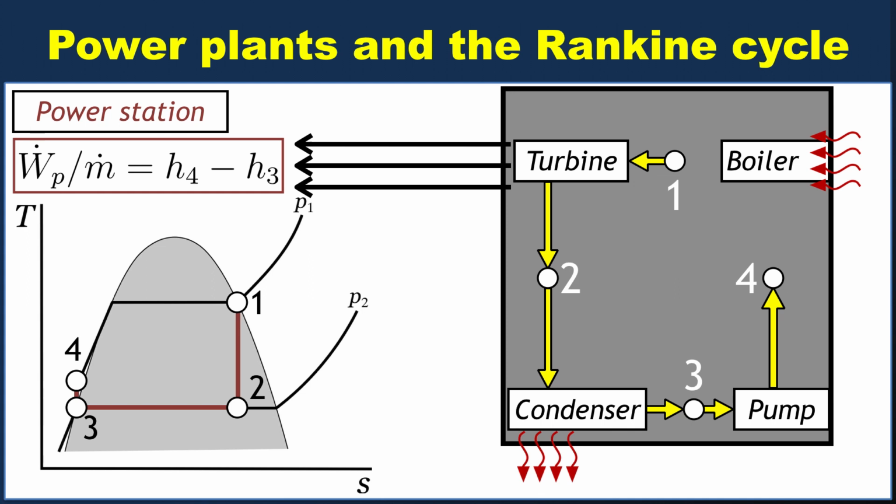If you want your pump to operate, you probably also want to plug it in. So we'll want to take some energy, whether it comes directly from the turbine in our plant or whether we just have some external power source, doesn't really matter, but we'll have some work into the pump in order to power it. Okay, so now we've reached state 4, and you can see now we have to be a compressed liquid, right? Because we were a saturated liquid in state 3, we went vertically upward, that means that we now have to be a compressed liquid.